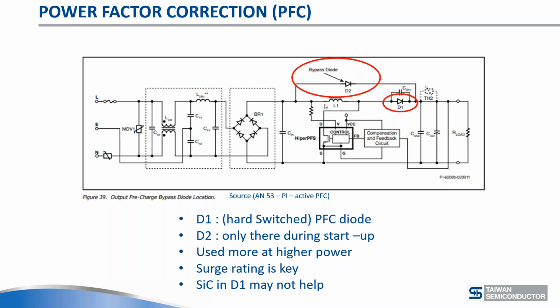So there is a modest current here. During startup, of course, you get current, maybe 100 or 200 amps or even more. And the circuit is not really laid out for that. So it does create, with the di/dt, all kinds of strange things which can lead to circuit failures. Also, the D1, the silicon carbide diode: silicon carbide has a positive temperature coefficient, and the die size tends to be very small, so they don't have a very good surge rating. So they can be thermally destroyed by the surge more easily than silicon.